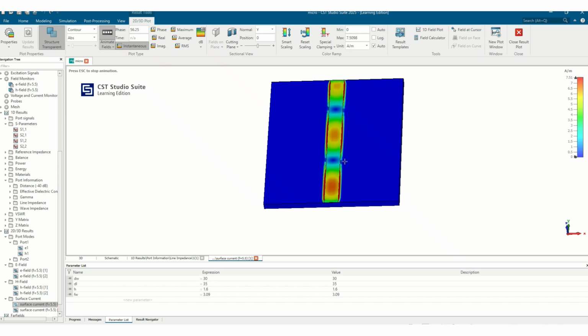If it is placed inside a PCB and there are some components coming near to this trace, this extended field will be affecting them. So the electromagnetic interference will be more if we are using these types of microstrip transmission lines. This is one of the disadvantages of the microstrip transmission line, these spurious radiations. If there are any other traces nearby, there is a chance of them getting affected.